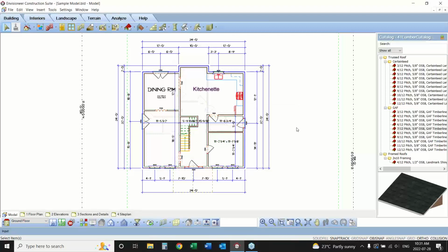The last thing that I want to do before we get into working drawing sheets is to cut my sections. You have to show it where you're cutting through the building to do your sections, and you do that here in model space, and then we insert the section views onto our working drawing sheets. So I'm going to be cutting 2 sections through our model, and I'll step you through that.